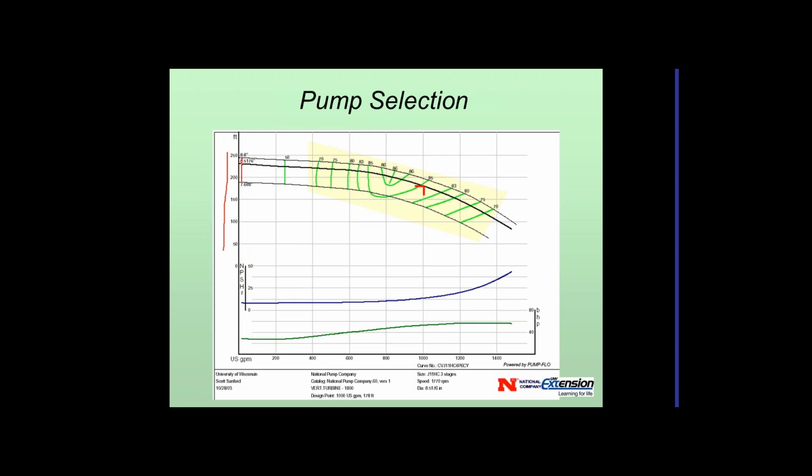So that's an example. This particular one, can you have a range of impeller sizes in it? The one that we're using is 8.5176 inches in diameter, and if we follow that around, this was designed for 1,000 gallons per minute, which is across the bottom here. So my operating point is going to be right here. It's about 175 feet of head at 1,000 gallons a minute. And at that point, it's going to have an efficiency of close to 85%.